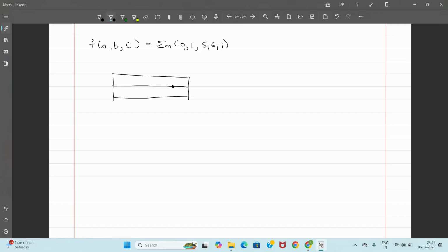So you know that if you have 3 variables, it means there are 8 possible combinations. So 8 cells. Let me take A for the row and B and C for the column. This is 00, 01, 11, 10. So B bar C bar, B bar C, B C, B C bar. The row is 0 or 1. One variable, so only 2 possible values, A bar or A. Then the cell numbers.